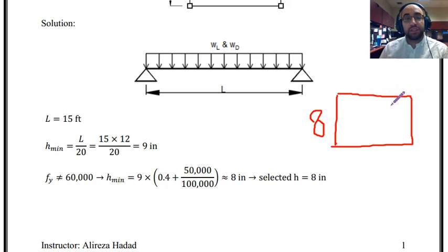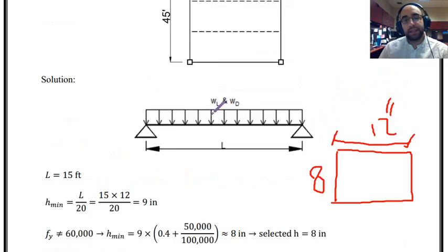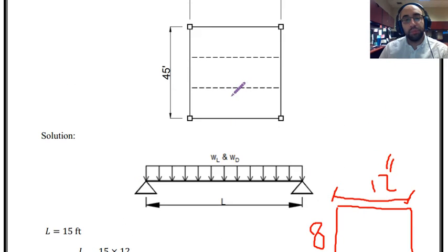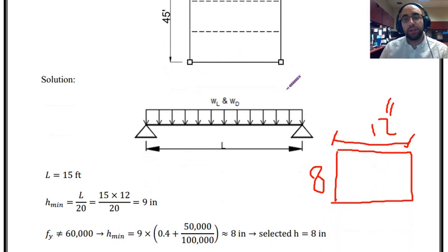But in this case we are designing a slab, and when we were talking about slabs, we said we are going to assume the width of a slab is always 12 inches. Because we said a slab is actually a wide beam, but we are going to consider some separate strips, some specific width in the slab, and based on that we consider the design section for the slab.